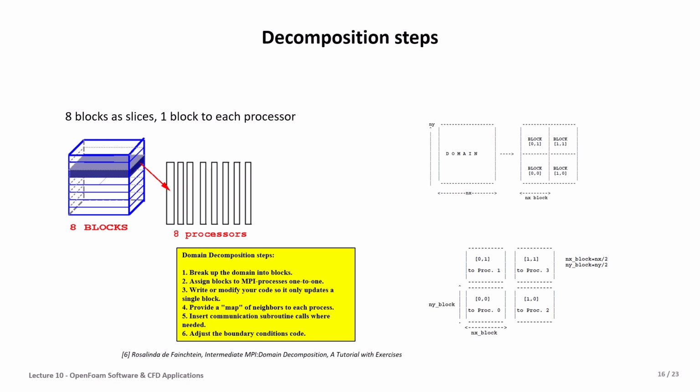Therefore, it's not a decomposition based only on the geometry. We need to look at the boundary condition, initial condition, and the geometry of the domain. Then we are able to make the decomposition. When we have unstructured meshing, it's also important that in some places there is a much more concentrated fine mesh, which gets us a much more accurate solution.